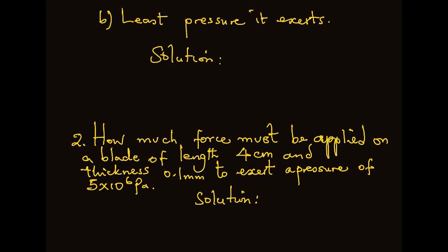Now we have already seen that pressure P is equal to force over area. If we have a box which is cuboid in shape and measures 0.2 by 0.1 by 0.05 meters, this box can be placed on different faces so that it is able to exert minimum and maximum pressures respectively.